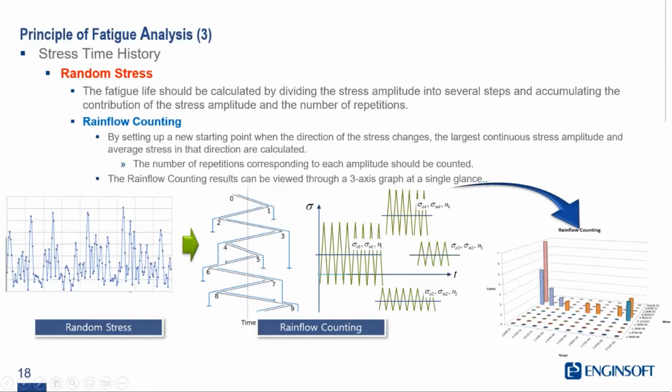We're taking some portion of this random stress signal, and it gives us a number of cycles for each of these curves here. The point of looking at it like this is you can see, okay, my primary impact is coming from a cycle at this frequency or at this frequency. That's what I need to focus on, rather than not having anywhere to focus your energy.